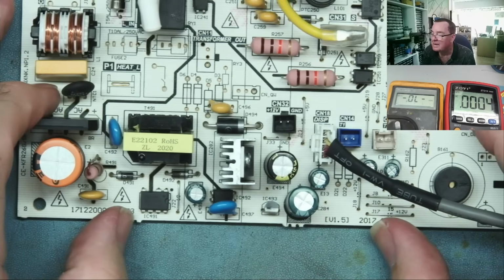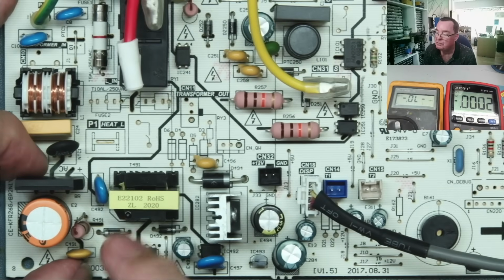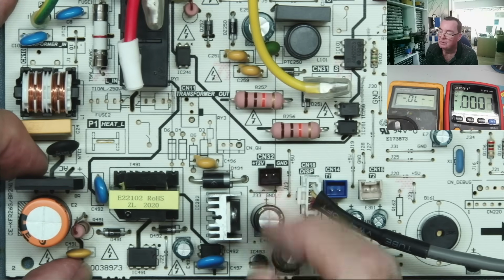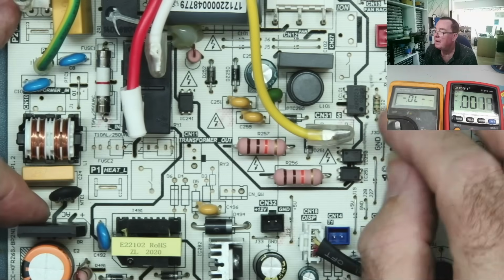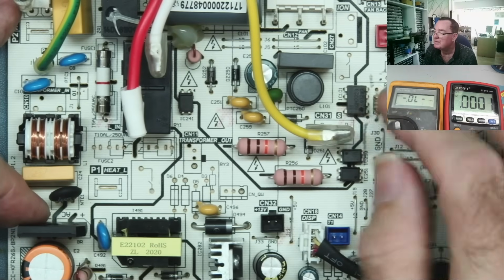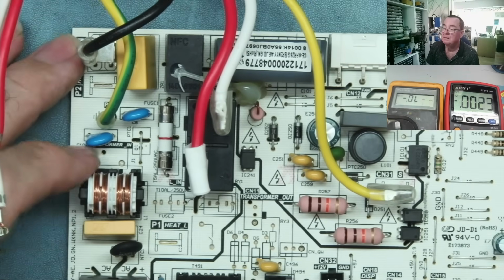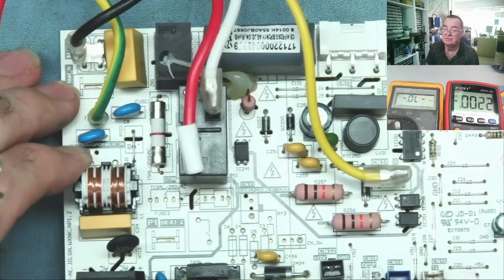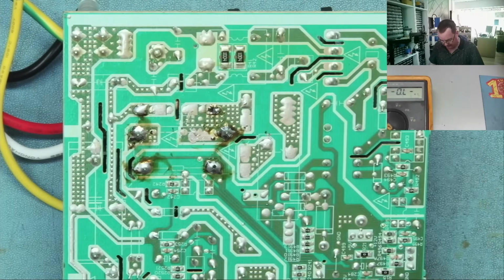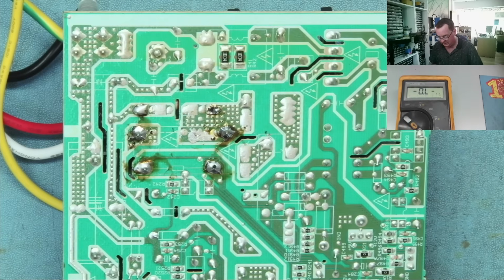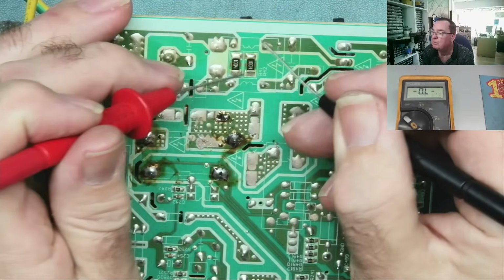Okay, so that's everything I can easily test on this side. We're just left with this and the regulator. I'm going to try and power this up. And we have this thing which will have to be taken off the board to test, okay? Right, let's look on the other side. Start again, resistors. I'm in ohms range again now on the meter, okay. I'm going to test any of the large looking ones.